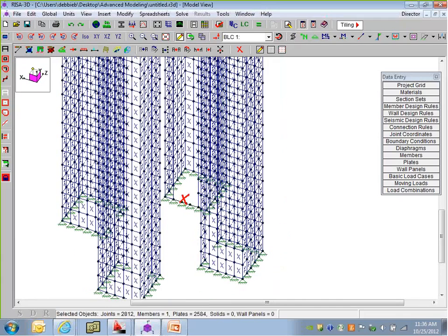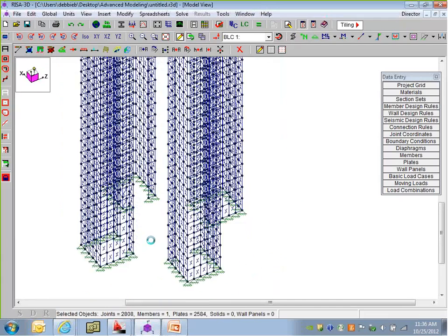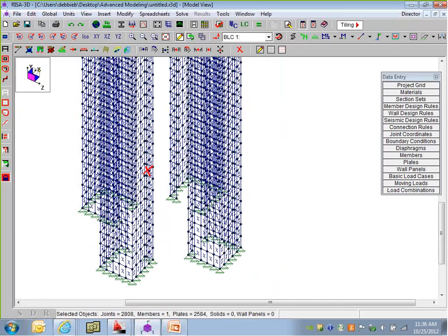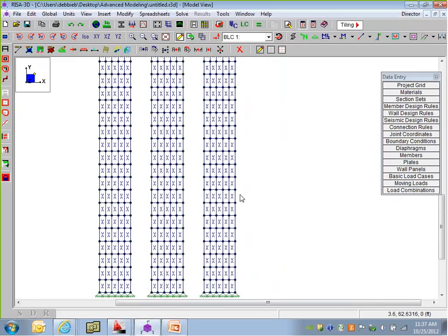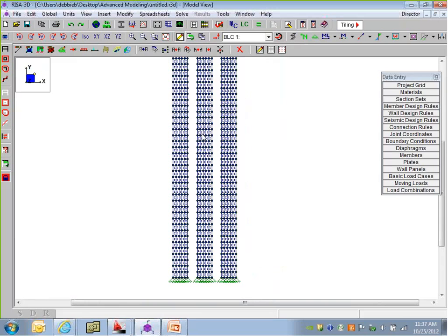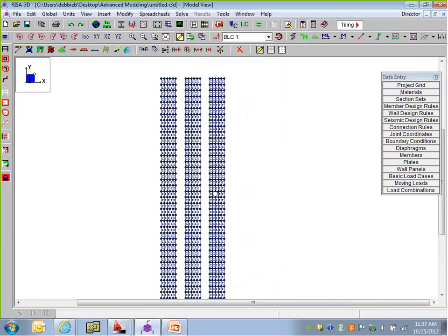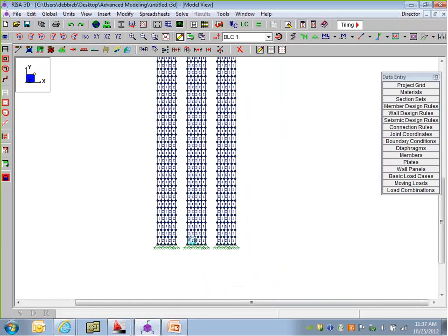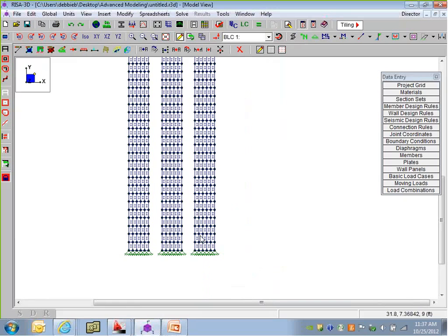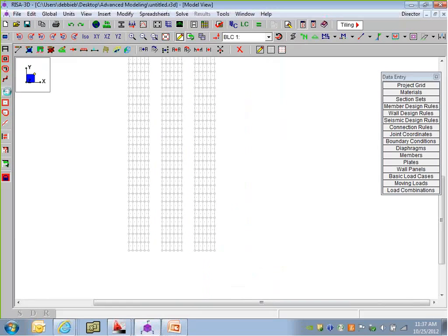Okay. So now, last piece here I want to do is I really am going to have to support these towers. And we're probably not going to freestand. We're going to have to kind of connect them so that they work as an actual unit rather than just singly, and really brace them. So what we'll do is let's look at this tower by itself. Again, every time I'm pushing selection, since I'm locked out, I'm not getting the top portion, which is nice. Okay, so what I'm going to do is unselect the tower. I'm going to go ahead and unselect everything and just select a portion of it.